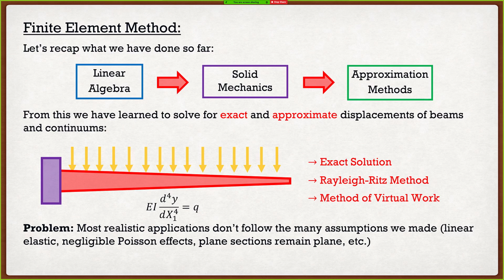So one of the ones I like to go with, because it's probably the most applicable for civil engineering, is concrete. Now concrete is really good for compression, and it's cheap. That's why we see a lot of concrete structures. However, in tension, concrete sucks. If I were to just put even service loads, everyday loads from regular people on the beam, it's going to crack. And if it starts cracking, that cross-section starts deteriorating. Therefore, the moment of inertia in a concrete beam changes depending on where you're looking at it.